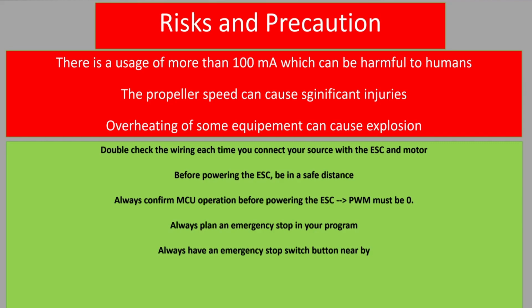Then always have an emergency stop switch, and this is what we had in our diagram. So we have an emergency stop, so we can cut the current immediately. And also keep others far from your system. When you're trying to do your experiment, be in a room by yourself, or make sure that everyone is far from you, so there are no people that can tamper with your system while you're working with it. And finally, if possible, wear safety glasses. So I hope you got the message here. We are going to work with some really cool stuff, but we have to be careful to enjoy the experience as much as possible.